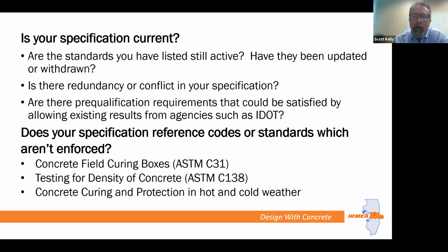We sometimes see low breaks on our projects, and this definitely will result in delays to move to the next phase of construction, while either coring or some other destructive or non-destructive testing is being performed to determine the in situ strength of the concrete. More often than not, if we look at how the cylinders were stored and handled on the project, we can trace it back to that.